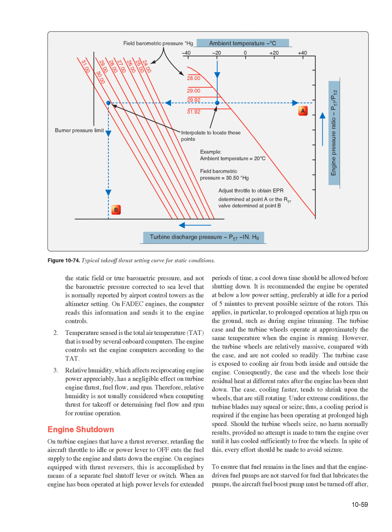Should the turbine wheel seize, no harm normally results, provided no attempt is made to turn the engine over until it has cooled sufficiently to free the wheels. In spite of this, every effort should be made to avoid seizure.